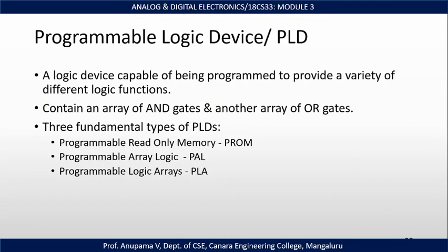A programmable logic device, that is PLD, is an electronic component used to build reconfigurable digital circuits. A logic device capable of being programmed to provide a variety of different logic functions is called a programmable logic device. A programmable logic device contains an array of AND gates and another array of OR gates. PLDs are semiconductor devices that can be programmed to obtain required logic functions. A device programmer blows fuses on the PLD to control each gate operation.